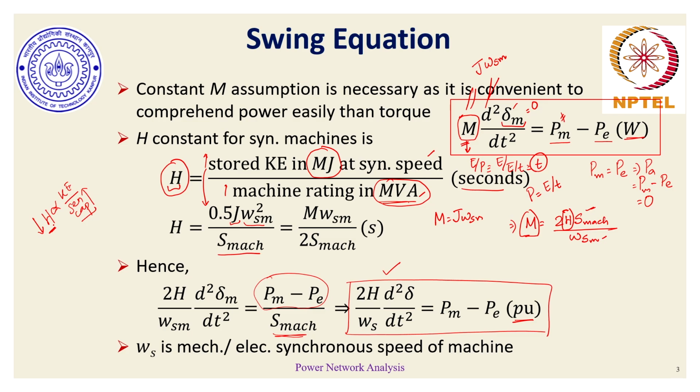So if the same disturbance is happening at some point, and we are trying to do the overall transient rotor angle stability analysis, specifically from the perspective of this rotor angle delta, which is being measured with respect to the rotating reference frame in the synchronous generator or analogous synchronous generator, then since the disturbance remains the same, the RHS quantity will more or less remain the same in both scenarios, be it with low penetration of renewables or high penetration of renewables. Because mechanical power is not changing, it will remain constant. The only term which would change is PE.